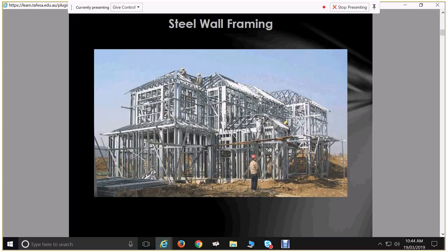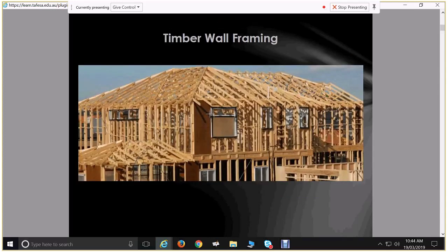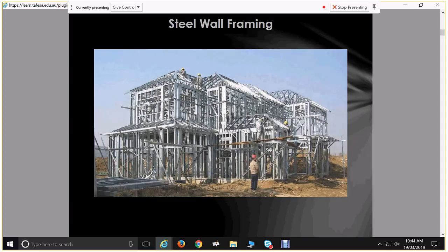This one, we have much the same stuff happening. If you look at both of these frames, essentially what's happening is a lot of the same stuff. We've got steel with essentially rafters at similar sort of spacing. So if that's a tile roof, they're going to be at 600. If it's a sheet roof, they're going to be at 1200. And we've got a lot of the same terminology. But what ends up happening with steel framing is, because the truss is a very materials-efficient approach through sharing a lot of its loads with everything,